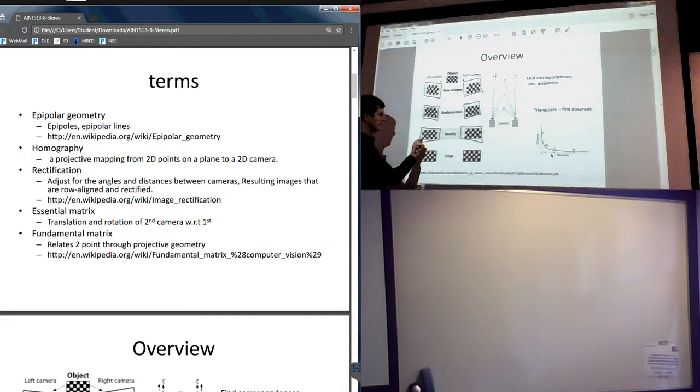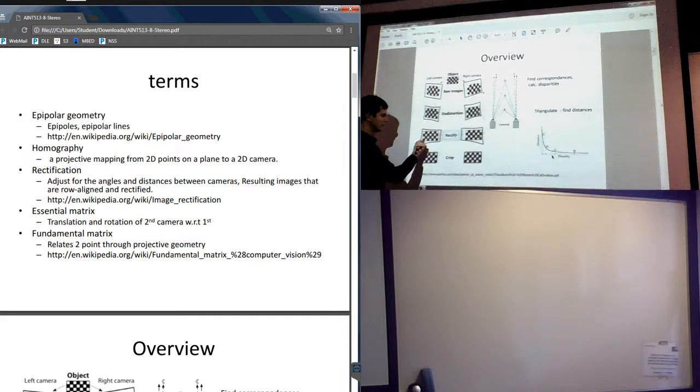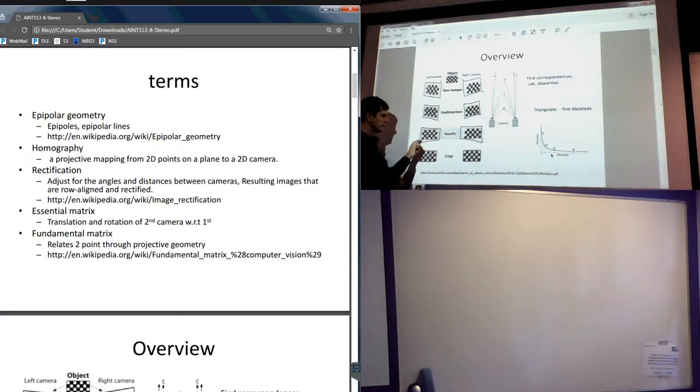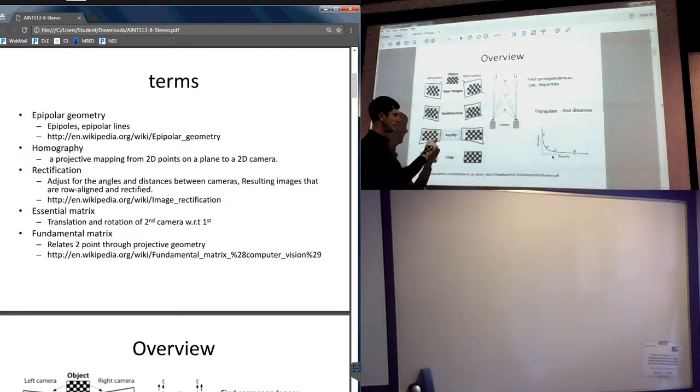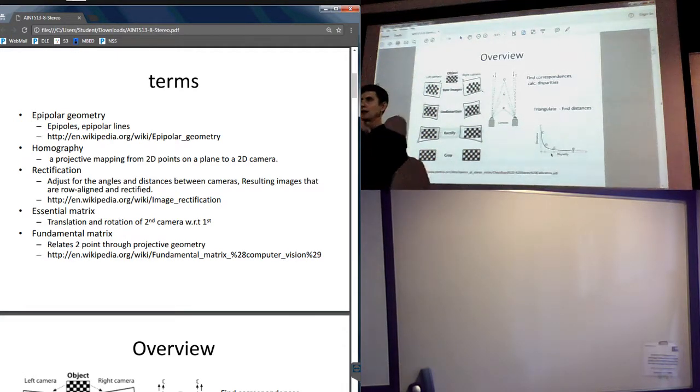This rectification allows us to project onto the left array and the right array of data. The same row in the left picture corresponds to the same field of view on the right picture. So if I'm the stereo camera and I'm looking straight ahead and I've had my lens distortions corrected and our eyes toe in automatically, but if I'm focused at infinity, they are perfectly parallel. And then down here on the baseline, I want to make sure that all of the pixels on the left camera map in some way to the pixels in the right camera.